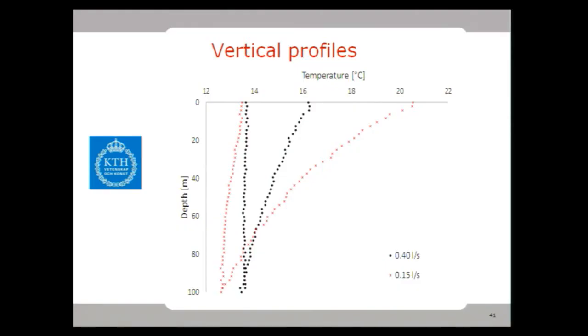We also find that the heat going through the central pipe, which is the insulated central pipe, was almost 0 during all the tests, evidencing that the insulation properly worked and that there was no shunt flow between down and upgoing fluids. So here, just as an illustration, I present the temperature profiles for two of the tested cases, low flow and a relatively high flow, giving you a picture of how the temperature distribution looks for these tests. We can see that the very low flow rate is when we start to see actually a shunt flow. Otherwise, the insulated pipe showed a good performance.